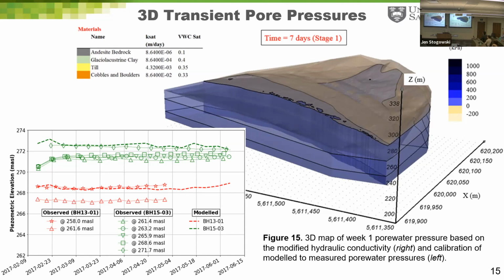Transient pore pressure changes were modeled at weekly intervals from February until June, when the river level reached its seasonal peak. This modeled time frame accounted for a 6.4 meter increase in Thompson River level. As a result, the division between the river head and land climate boundary condition had to be altered weekly to reflect the variable boundary conditions that are critical to groundwater flow at this site.